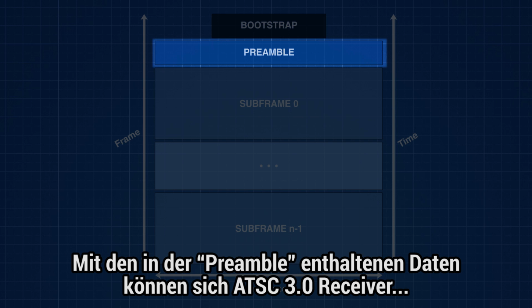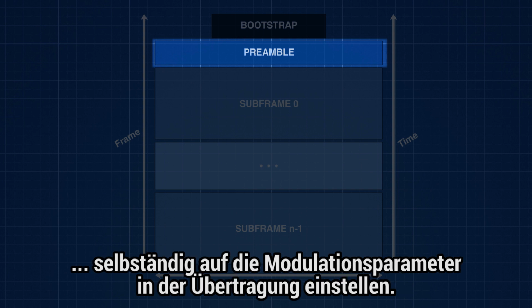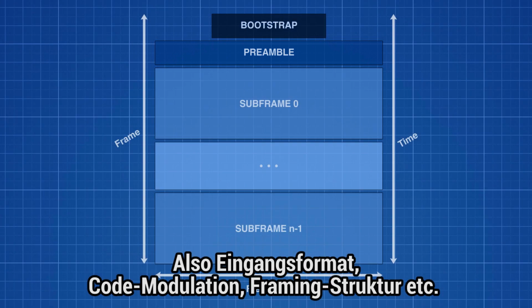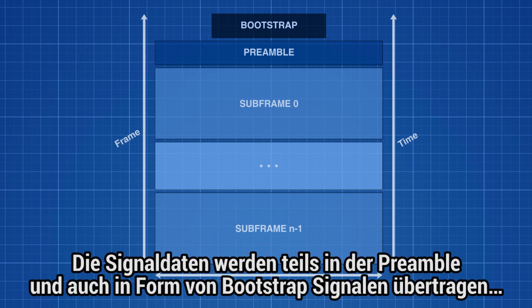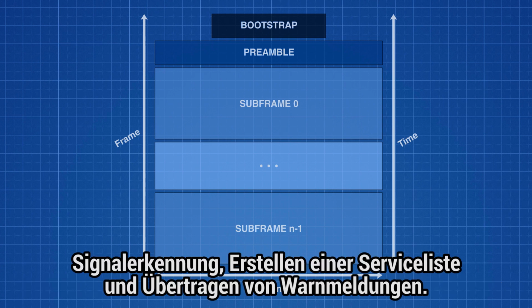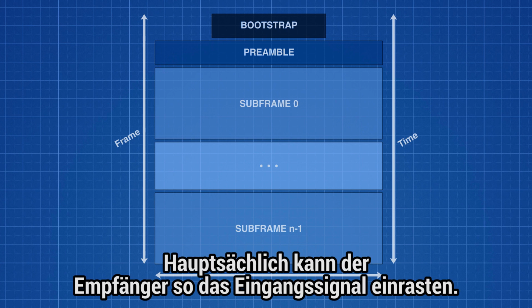The preamble is a part of the ATSC 3.0 signal that carries data that allows ATSC 3.0 receivers to tune themselves to the modulation parameters used for transmission, that is, input formatting, code modulation, framing structure, etc. The signaling data is transmitted partly in the preamble, as well as in the form of bootstrap signals. The latter is a robust signal that allows the receiver to estimate the RF channel, discover and decode the received signal, put together a service list, and convey emergency alert system alerts. But its most imperative function is to allow the receiver to lock to the received ATSC 3.0 signal.